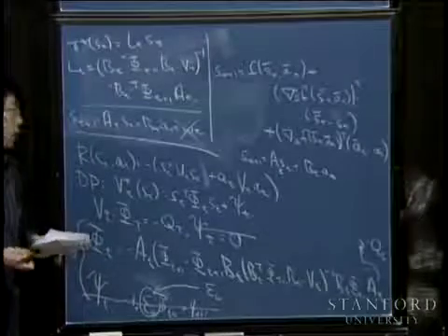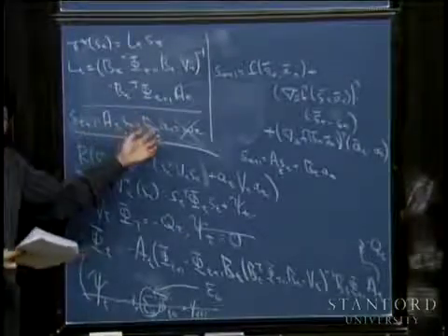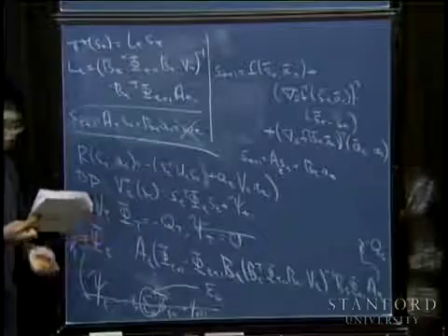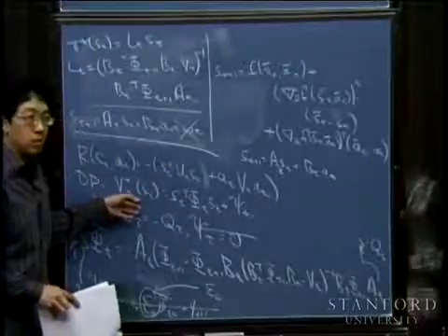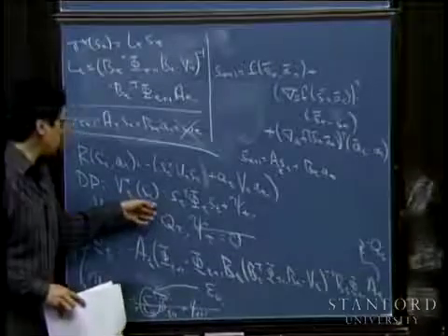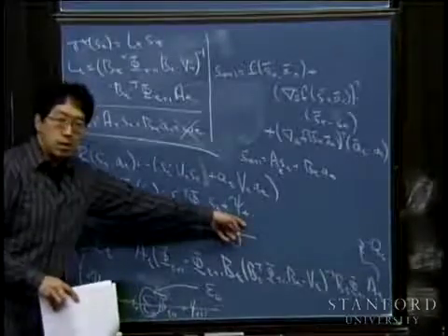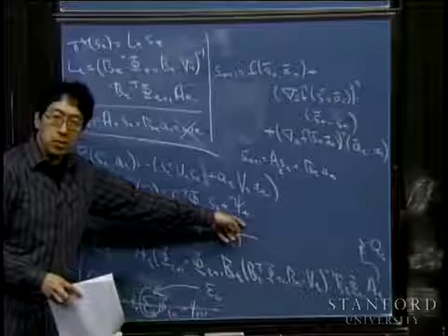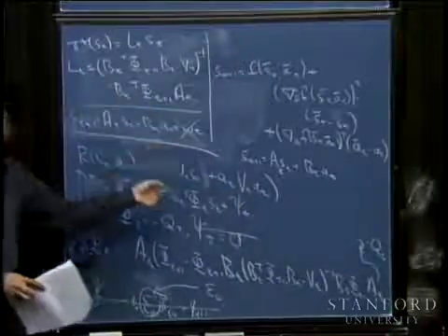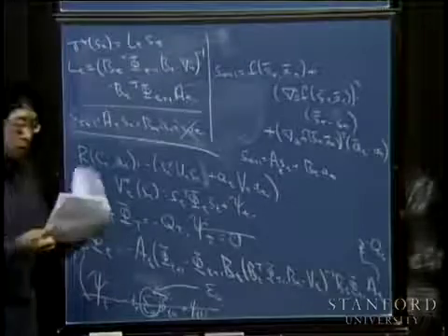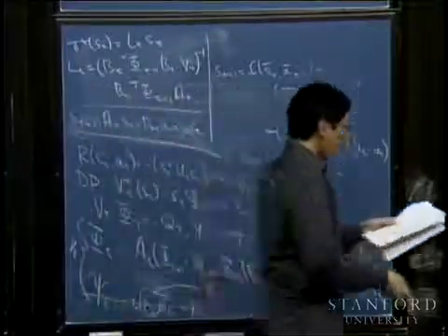Later on, when we talk about Kalman filters, we'll actually use this property of LQR systems. Just to point out, note that the value function does depend on the noise covariance. Right, the value function here does depend on psi_t, and so the larger the noise in your system, the worse your value function. So this does depend on the noise, but it's the optimal policy that doesn't depend on the noise. I'll use this property later.